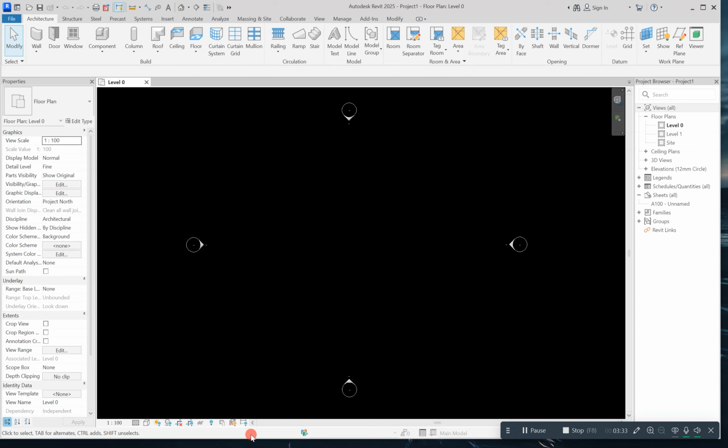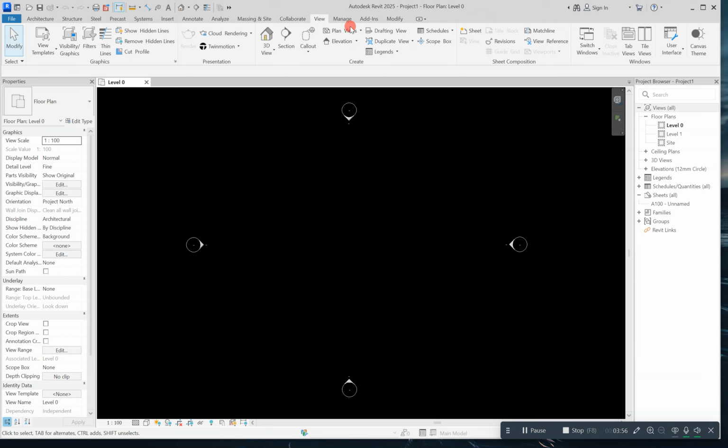Maybe what I would advise is that you might open a file, or a colleague might use your computer and bring it back when some of these ribbons are not there. So how do you get them back? To get these ribbons back, you're going to go to view on your taskbar up here. Then on your top right, you go to user interface. So below here, you're going to see where you can either turn on or off the ribbons that you want to work with.